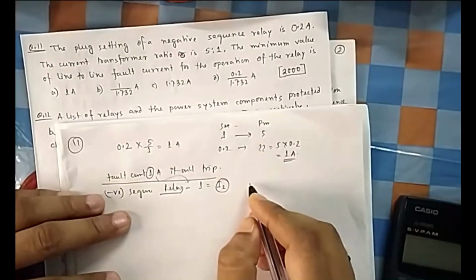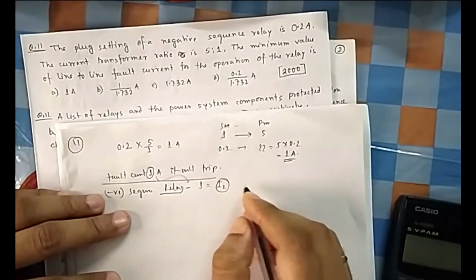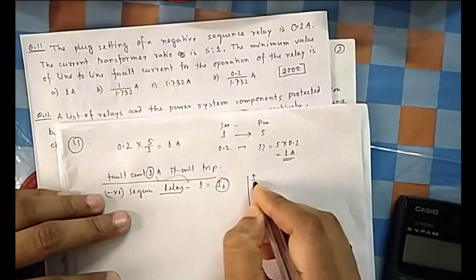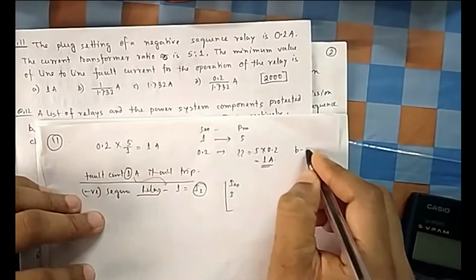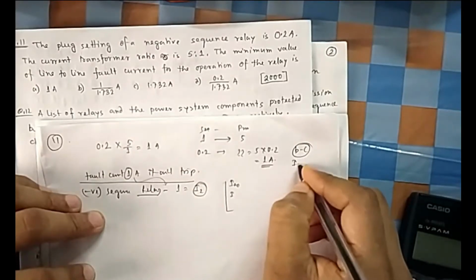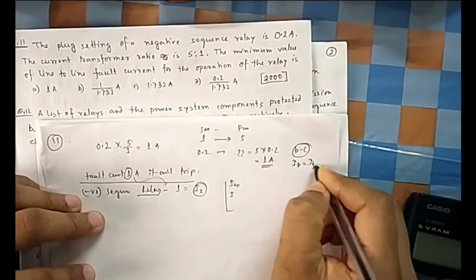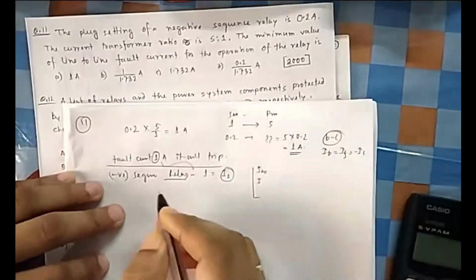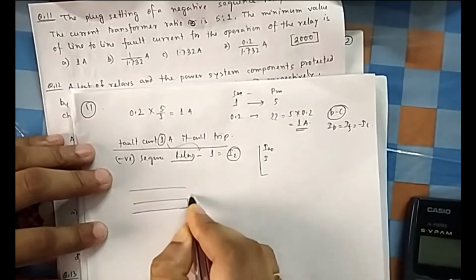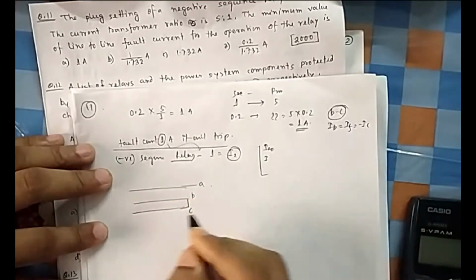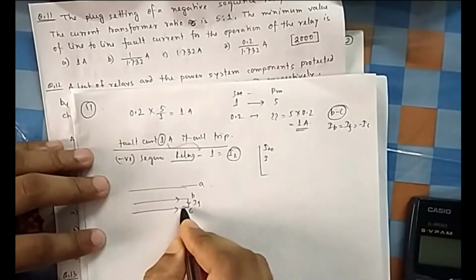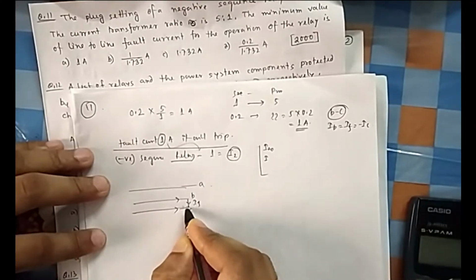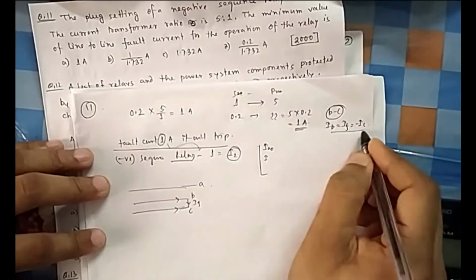So if you see from your symmetrical component analysis, this was your Ia0. I am taking a standard line to line fault, that is a fault between B and C. So what is your Ib? Ib is equal to If, which is equal to minus Ic. You can think of it this way: there are two lines, B and C are shorted, so A is separated. So this is the fault current If, which is nothing but Ib, and Ic, because the fault current is flowing against C.